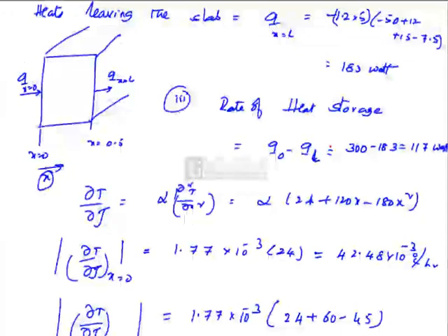That means at x = L, the slab is getting cooled faster than at x = 0. But the rate of cooling or heating is maximum, in fact, at a location of x = 0.33 meters measured from x = 0, where the temperature changes are maximum. Quickly the temperature is changing at x = 0.33 meters. So as a whole, what we have to understand is that unsteady state conditions are prevailing. That is, the temperature at any location within the slab is not constant. It is changing with respect to time. At some locations, the change is much more than at other locations. Hence the problem.